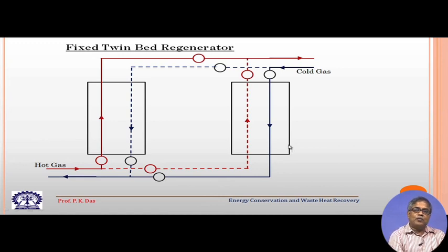Generally these are porous materials. So, they will have a solid component which can store thermal energy. They should be good at storing thermal energy, but at the same time, these beds will have porosity or some sort of interconnected channels through which the fluid stream can pass. In most applications the fluid stream is some sort of gas, so we have two gas streams.